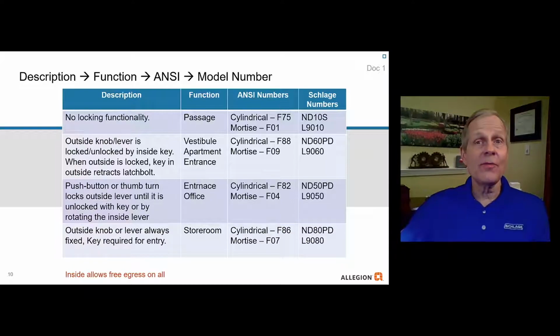Next one is a storeroom function. We already discussed that one. That one is locked at all times. You insert the key, turn it, it momentarily retracts the latch. As soon as you pull the key out, it relocks. There is no push button on the inside. The inside is always free for immediate egress.